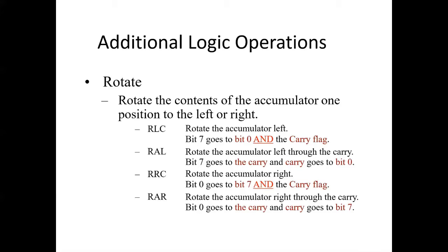This instruction is useful to check the value of LS bit of accumulator and perform rotate right operation. It is also useful to perform division by 2. It works correctly for unsigned numbers as long as the LS bit of accumulator and the carry flag are 0 before rotation. It is also used to introduce a new bit value to the MS bit position and put this bit value in the carry flag and then execute this instruction.